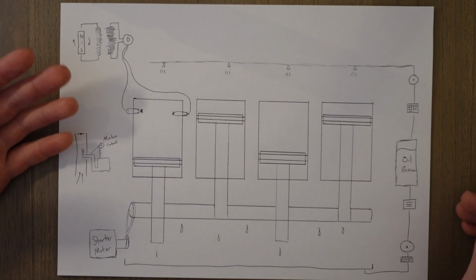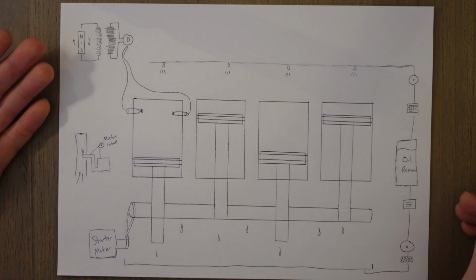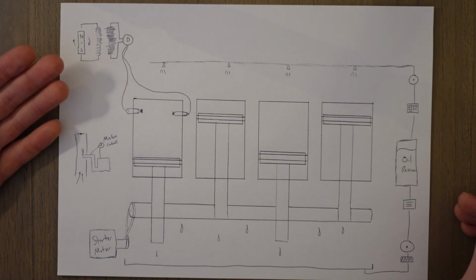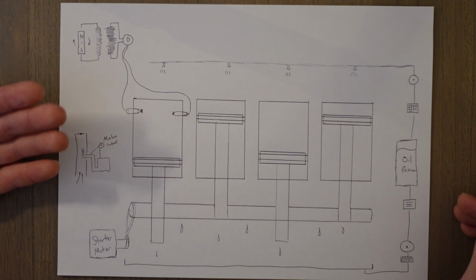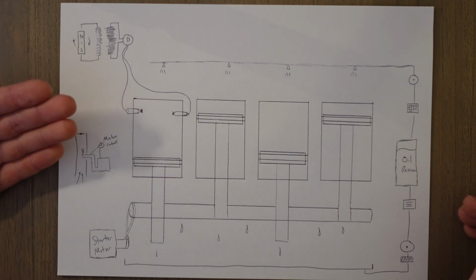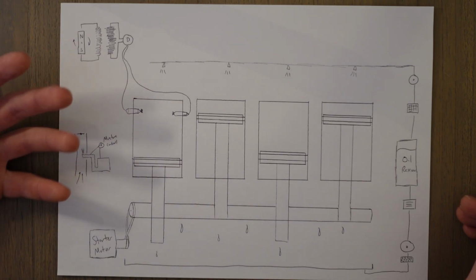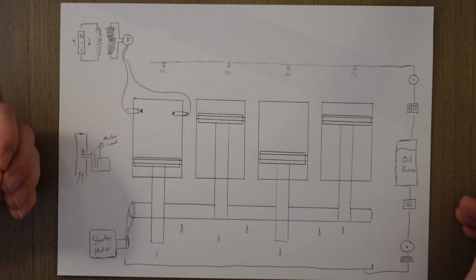Fuel mixture is very important. If we have a rich mixture, it can help to cool the engine, but comes with the trade-off of burning more fuel. And if we have a lean mixture, it is very good for fuel efficiency, in those situations where we don't have to use maximum power, all the power that the engine can give.